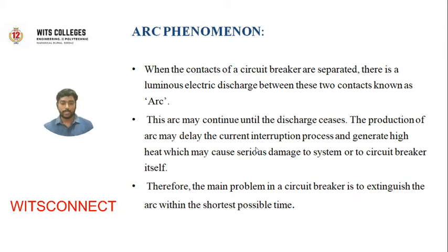A circuit breaker consists of two contacts, fixed contacts and moving contact. In normal condition these two are closed. When the moving and fixed contacts are closed, it is a continuity path, and current flows to the load. In abnormal condition, when a fault exists on the system, such as overload or short circuit, what will happen? The fault produces heat.